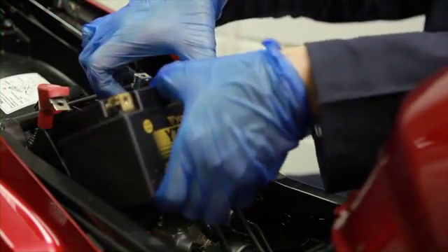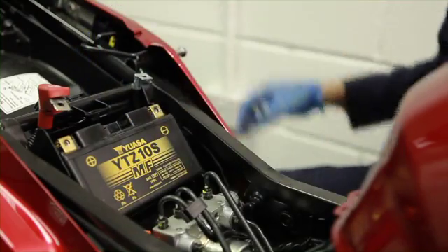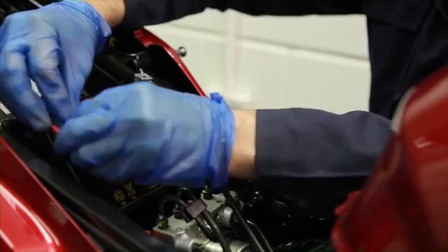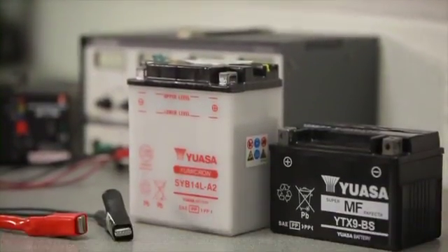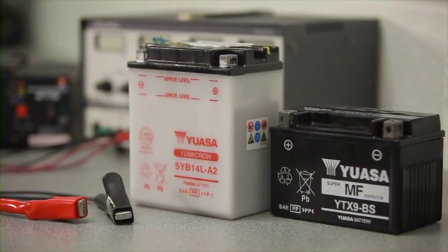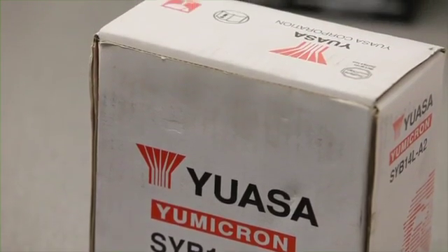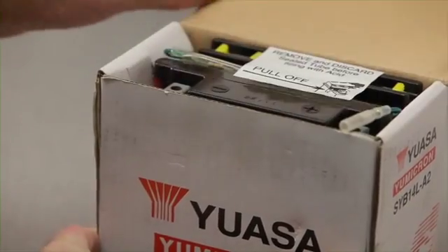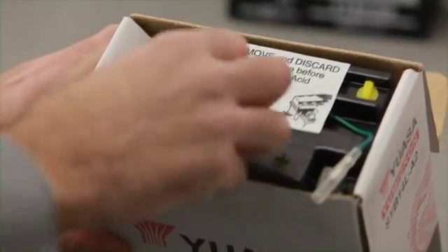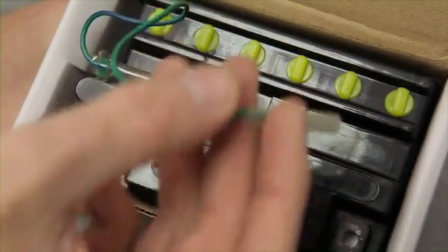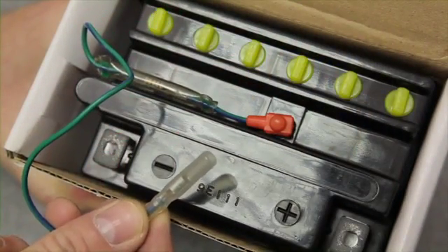Installing the correct recommended battery for a vehicle is important. Fitting the wrong product can cause battery failure and may lead to unnecessary warranty claims. Never install a conventional battery in a vehicle equipped with a sealed battery. They are different and are designed to meet specific requirements and needs. Some batteries are equipped with a sensor which will activate a warning light in the instrument cluster indicating when the battery is low on electrolyte. As a general rule, the sensor and the battery should be replaced at the same time.